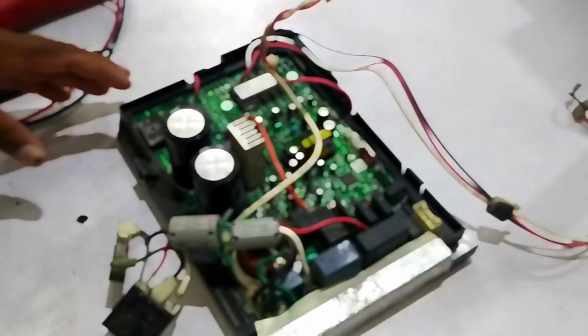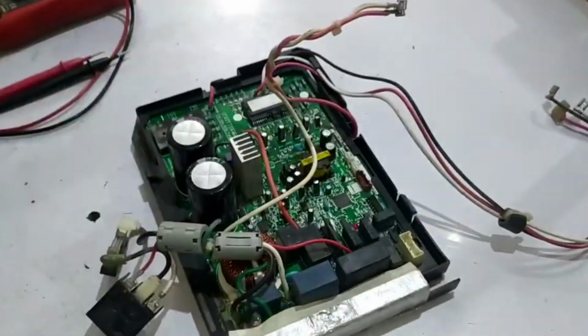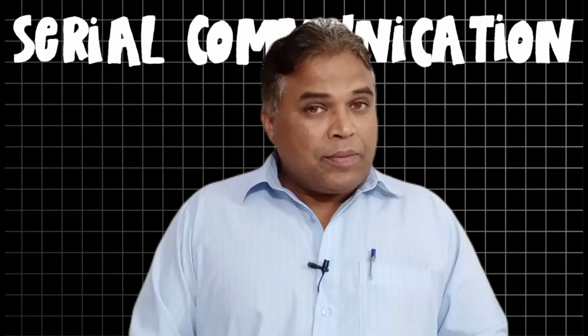Now let me explain another possible fault. If you have started the unit and the relay has switched, but the error appears afterward, it means the problem is in the outdoor unit. In this case, you need to inspect the outdoor unit to identify the exact issue. Now, let's discuss the possible faults in the outdoor unit. To diagnose the issue, we have already opened the outdoor PCB for inspection. However, before identifying the exact fault, the first step is to check whether the serial communication is functioning properly.